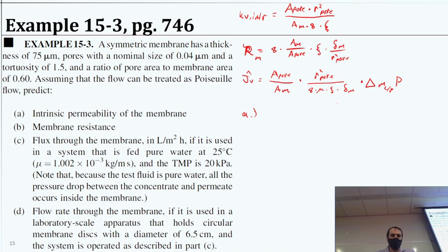the intrinsic permeability of the membrane, we're essentially given the dimensions, so it would be a matter of applying this equation, making sure our units are consistent. I think it's probably best to work with meters directly in pretty much all cases, because most of them will be dealing with mu, and even our pressure units are going to relate to meters. Pascals are in terms of newtons, which are in terms of meters. So basically we want to make sure we're converting appropriately in almost every case.